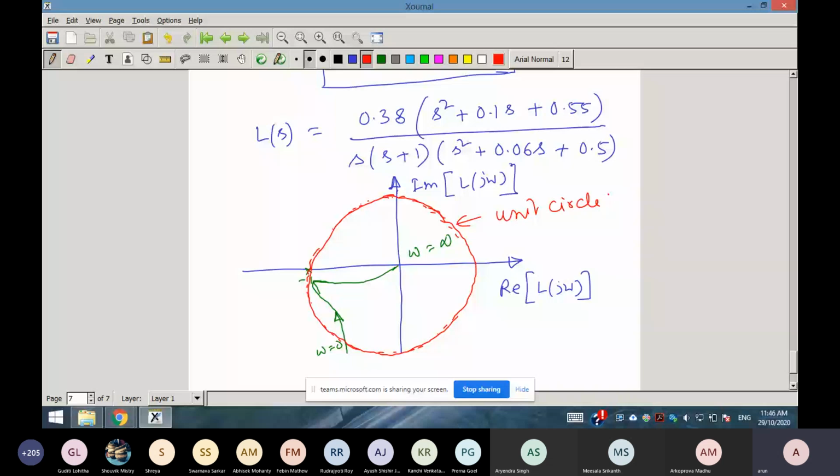So you can verify that. So here this is your phase margin, this is your phi. So phi will be almost phase margin equal to 70 degree, and here you can easily see what is the gain margin. Upper side gain margin is infinity, and lower side gain margin is arbitrarily small. So gain margin, I am writing here infinity, means upper side. And lower side gain margin also you can make arbitrarily small. From the figure it is also clear.